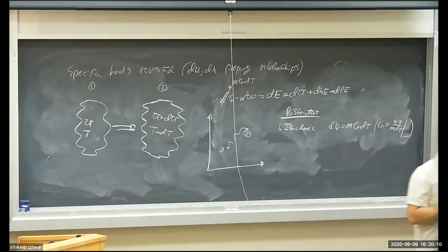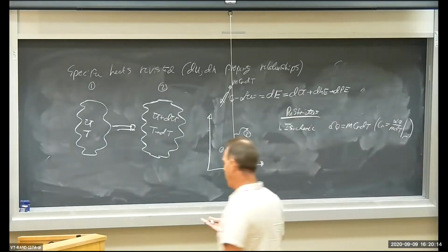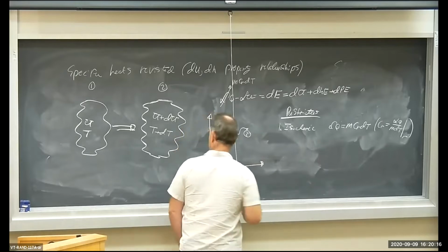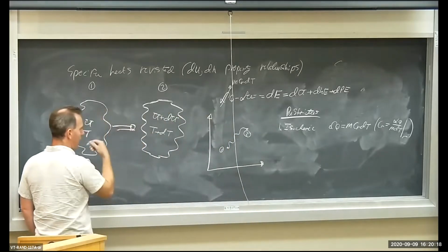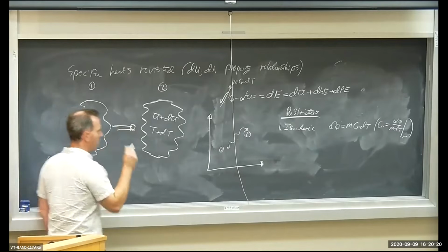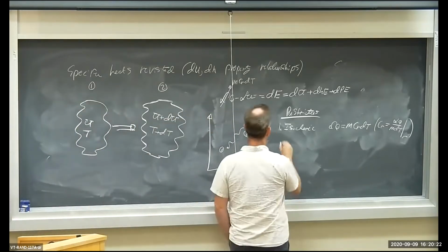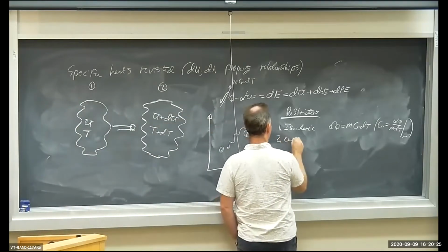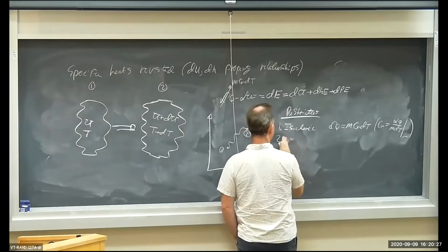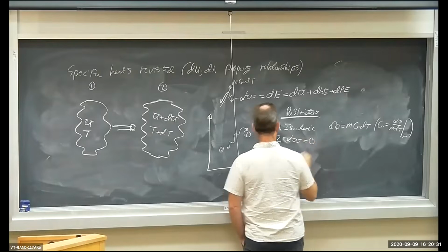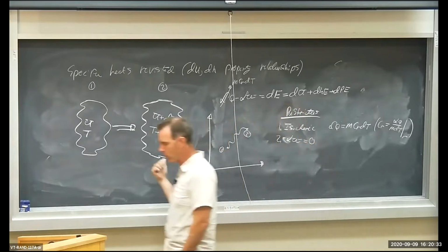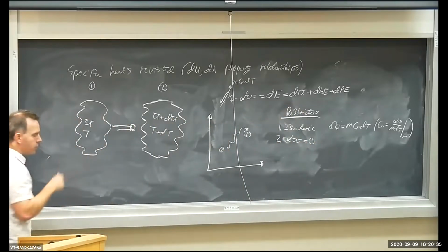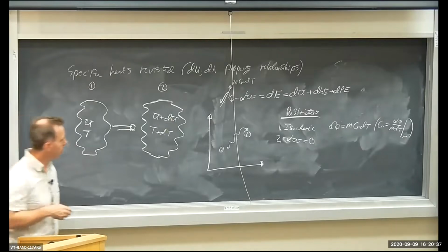By the way, if it's isochoric, what's the boundary work? It's 0, no boundary work. In fact, I don't see any wires or shafts in this system. So all work, or differential work, is equal to 0. No shafts, no wires, isochoric, no boundary work. So there's no work going on, and this term is equal to 0.